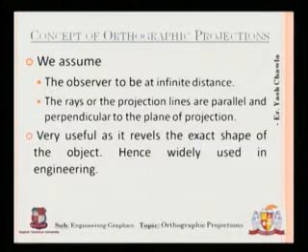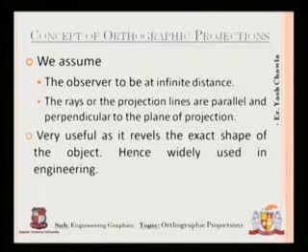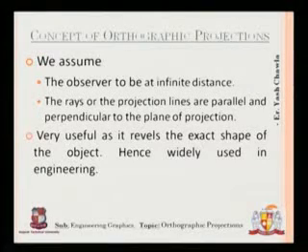As you know, if a ray of light is parallel to one plane of projection, principal plane of projection, then it will be perpendicular to the other principal plane of projection. So we'll have different views, that is front view, top view and side view. And in side view, if a line is parallel to the vertical as well as the horizontal plane, then it will be perpendicular to the profile plane. So the concept applies to all the three principal planes. So first of all, let's have different views.